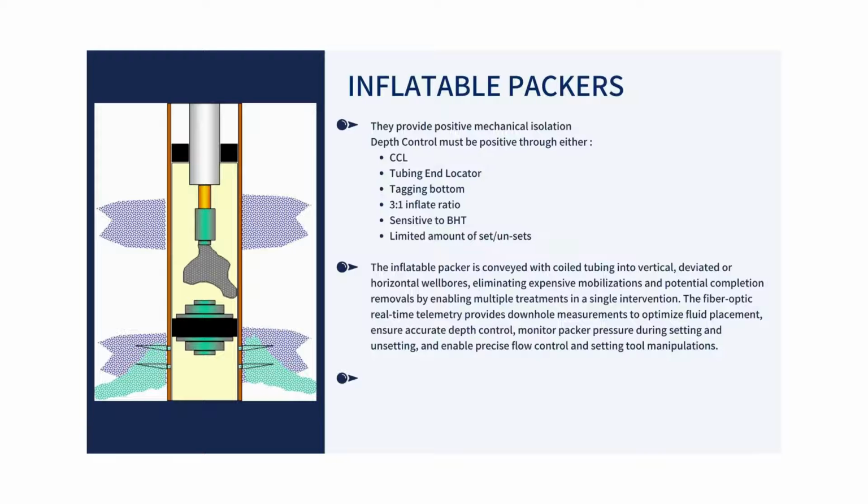The inflatable packer is conveyed with coiled tubing into vertical, deviated or horizontal wellbores, eliminating expensive mobilizations and potential completion removals by enabling multiple treatments in a single intervention. The fiber optic real-time telemetry provides downhole measurements to optimize fluid placement, ensure accurate depth control, monitor packer pressure during setting and unsetting, and enable precise flow control and setting tool manipulations.